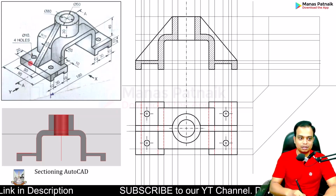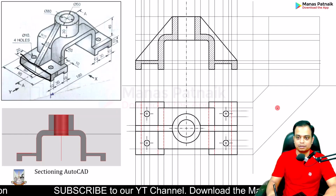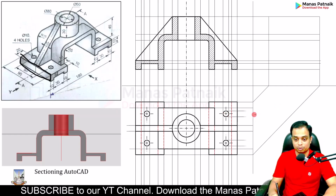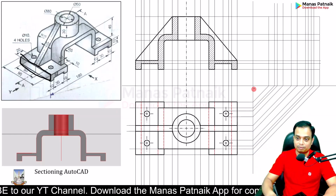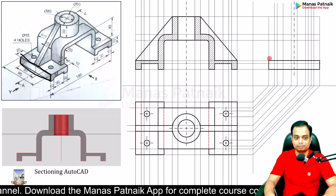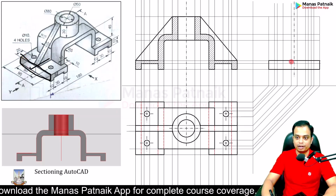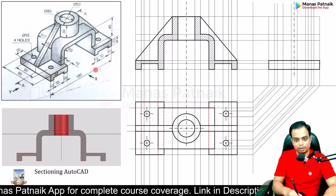Side view is very easy. What you see initially is this. I need to produce lines, rotate them at 45 degrees, and produce them in the upward direction. The first step is this: center line. Done. Can you relate? Yes, sir. Secondly, there is a hidden edge 5 mm below.